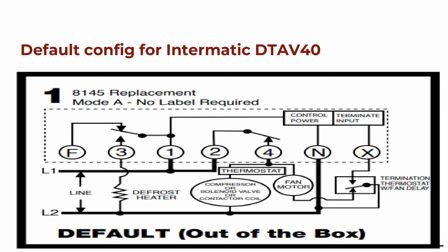Now when defrost is finished, one of two things is going to happen in order for defrost to terminate. Either the time clock is going to time out, so we've set it to 15-minute intervals and we have passed the time for those 15-minute intervals. Now all of our switches are going to return to their original positions. Power will return to the compressor, and power would return to the fan motor if it were just terminated off of the time clock alone.